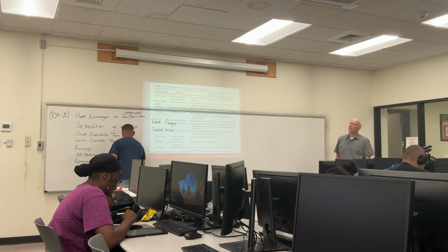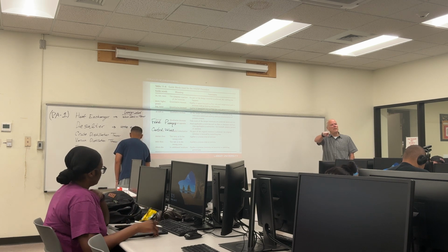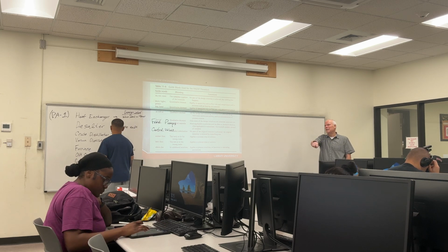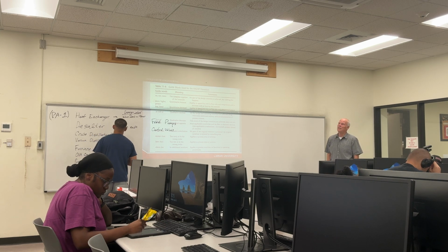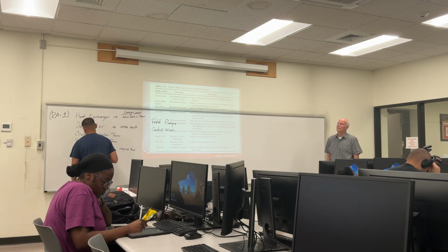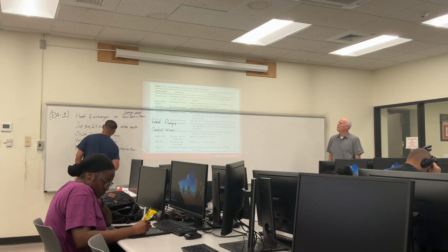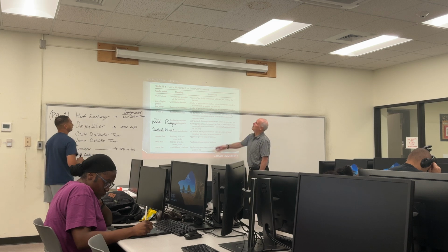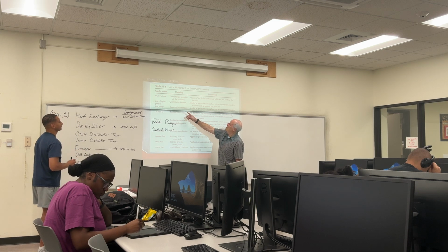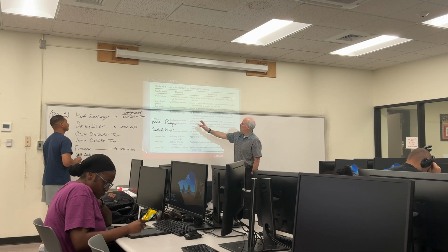So that's the first step. You need to list every single piece of equipment in your project and come up with a design intent for that piece of equipment. You can't really do this process if you don't know what the intention is, because all of this is about the intention.